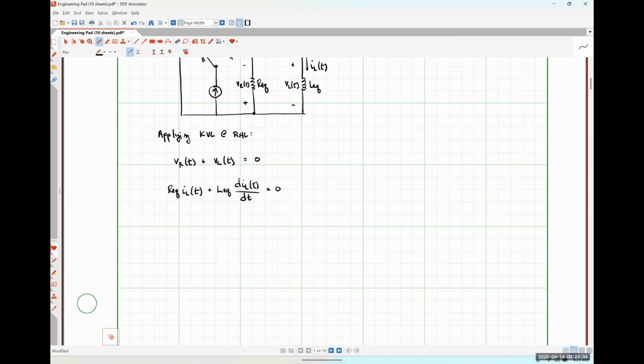So I'm looking for a function where the function plus its derivative might come out to equal 0. So the function and its derivative need to be effectively of the same form. So what kind of functions do we know that behave that way? I heard somebody, yes. An exponential function, absolutely. So let's say that we're going to take a guess, and this is an educated guess, but it's a guess nonetheless, that IL of t will be of the form A e